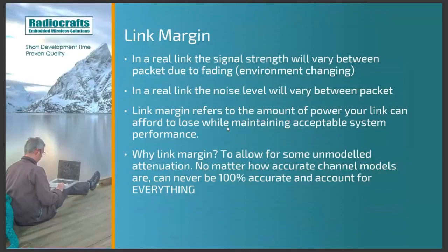If you send one radio packet and 10 seconds later send a new one, it might come to the receiver with a completely different signal strength. When we were doing outdoor tests in Oslo with our radio systems, with a person walking with a device on the street, every time a bus drove by, we saw the signal level drop significantly.